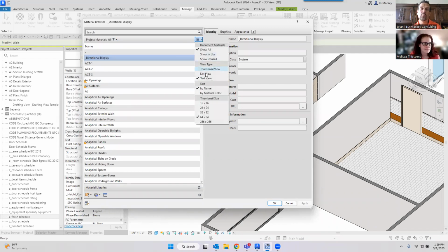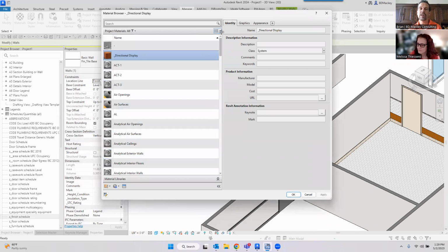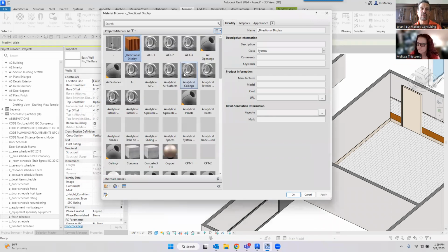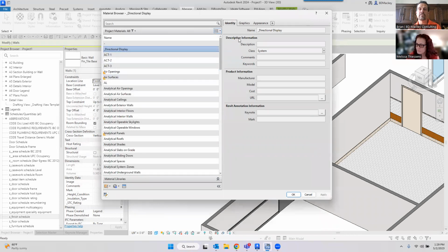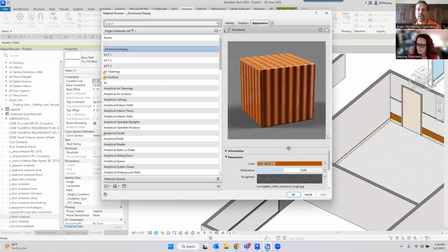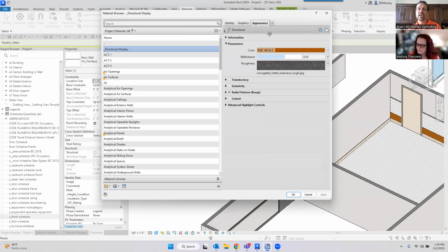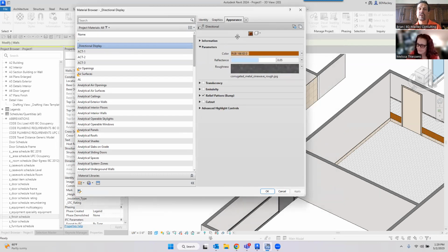There are 2 reasons for this. One, every time you have an icon on there, when you open up the dialog box, Revit has to regenerate all of those icons, right? So if you're set up here to thumbnail view and you're seeing all these giant pieces, it's going to regenerate all of those. So for me, I am always in text view. I do the same thing on the appearance. I see people grabbing this and pulling it down like this because they want their appearance to be really, really giant and large. I don't care 90% of the time when I'm working on appearance. I drag it all the way up to where there's nothing there.